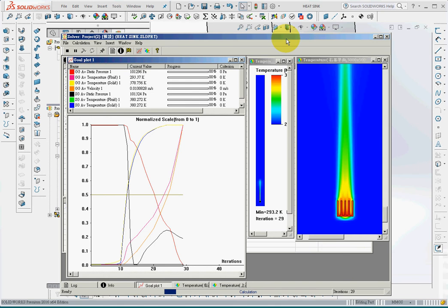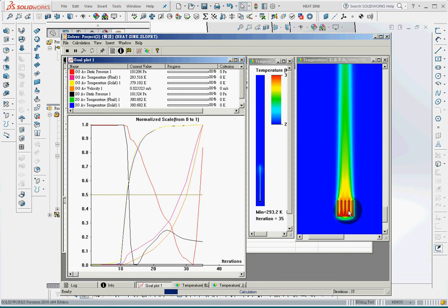As you can see from the solver window, the hot air goes upward because of the gravity in the Z direction. If you forget to define gravity, or you define gravity in the wrong axis, the air will go down or go sideways, so you know that the gravity direction is wrong.